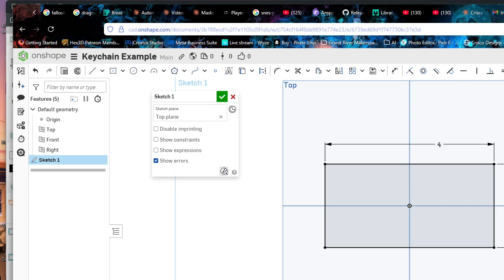Basically, if you see blue, you have to try to define your object a little bit more. Now let's say I'm doing this as a basic keychain. A keychain will have a hole in it for a ring. Some people might design the whole shebang, like I might put a little rectangle here for the ring. I tend to piecemeal things a little bit more so that when I go to walk things back, each feature is defined by its own modeling entity. So I try not to stack too many things of a design into one.